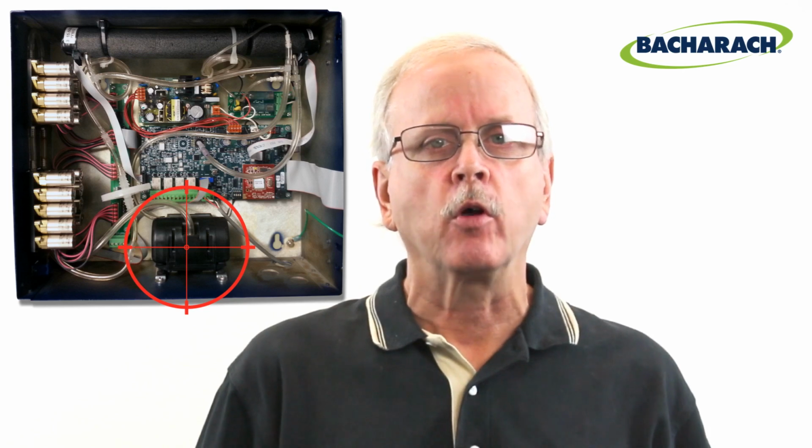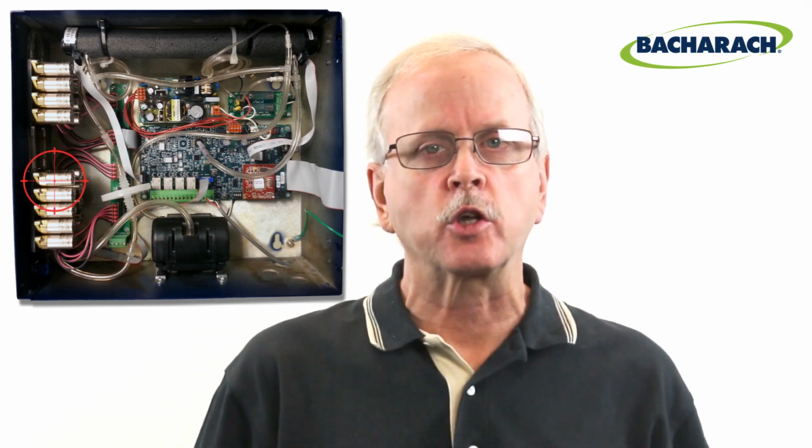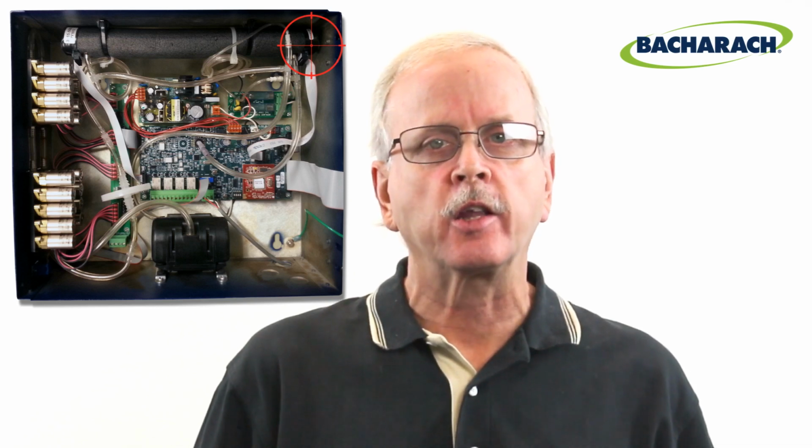The multi-zone gas monitor takes up to 16 zone samples in a continuous round-robin fashion. Using the onboard pump, the MZ draws in a gas sample from the next sequential zone into the infrared bench, analyzes the sample, reports results, and then moves to the next zone. Depending on the sample line length, the number of zones, and how often you configure the system to re-zero, a complete cycle of all zones may take several minutes.